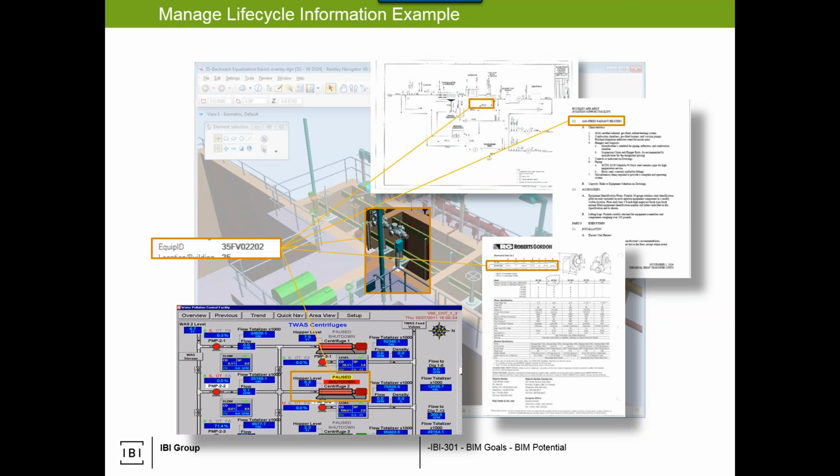It's X, Y, Z. But then its unique identifier springboards the BIM model to other forms of information, whether it's drawings that come from the model itself, parallel intelligent schematics, specifications, operations and maintenance guidance and documents that are brought throughout the duration of the project, or possibly operational or facility management screens that are used to run the building. And all of that is interrelated based on a unique identifier attached to an object.